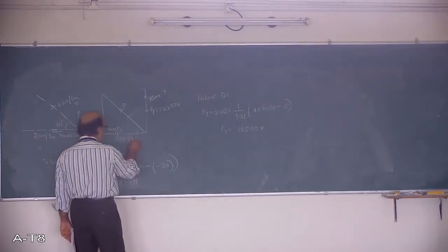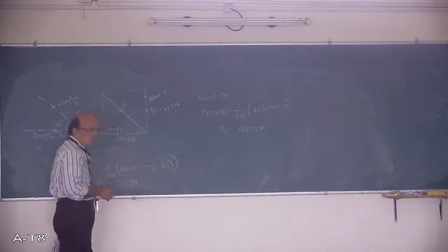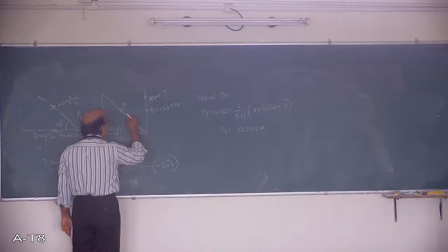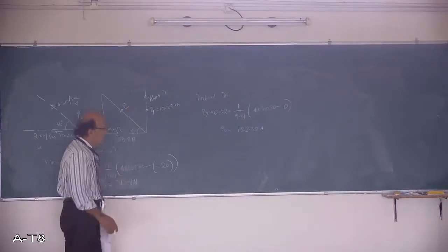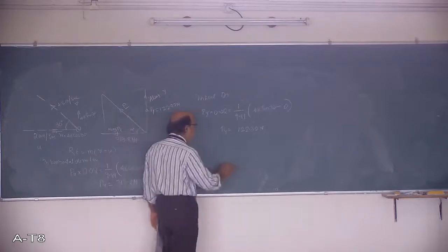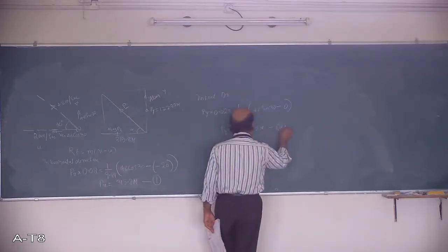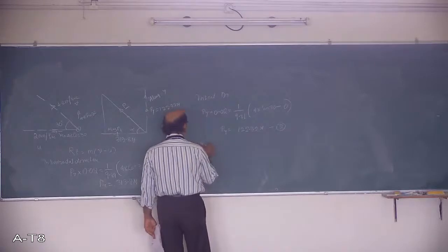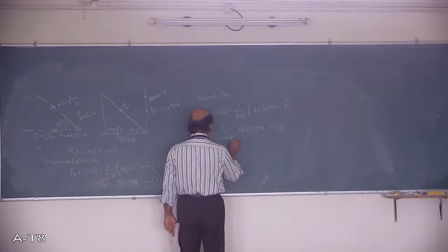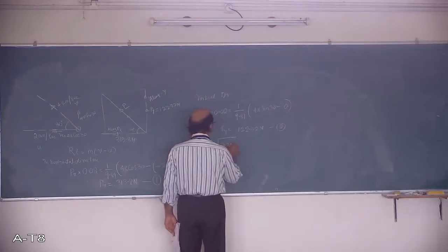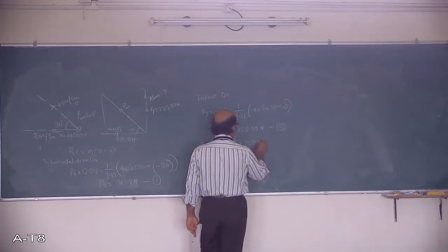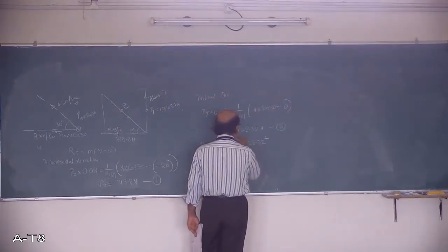And this is 313.8 Newton. Now once I know these two forces, by parallelogram I can work out this angle alpha, and I can work out this P also. From these two equations, answer 1 and answer 2, I got P equal to the square root of 313.8 square plus 122.32 square.